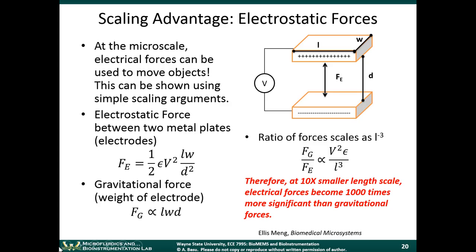The electric force is equal to 1/2 times epsilon, the dielectric constant of air, times V squared, where V is the voltage being applied between the two plates, times L and W, the length and width of the plates, divided by D, the distance between the two plates.